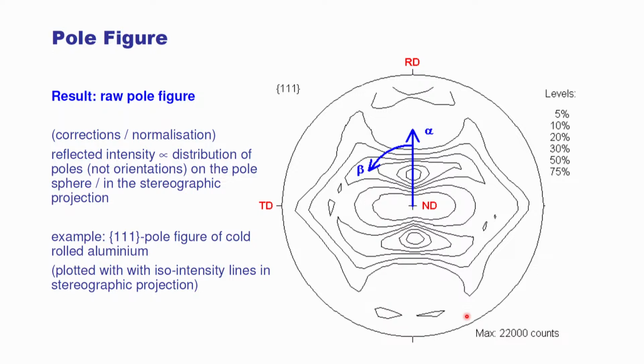Electron diffraction in the TEM can be done similar to this. It's kind of screwy, you get a slightly different type of view, but it can be done. And with EBSD or with electron spot patterns, we're getting single orientation measurements. We can't measure a pole figure directly. We basically measure a more complete function than this, and then we back-calculate these if we want to see a pole figure. So we'll talk about that coming up. But this is just measurement of a pole figure by X-ray diffraction. This kind of measurement started in the 1950s, and it's been going on. We still do X-ray pole figure measurements.